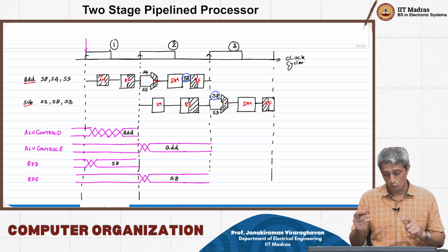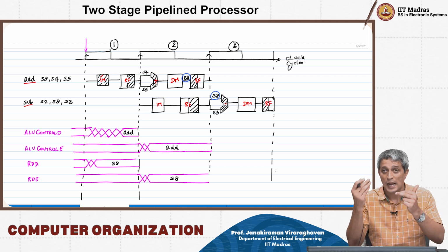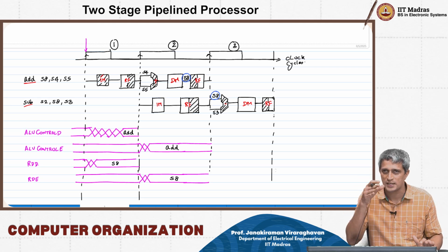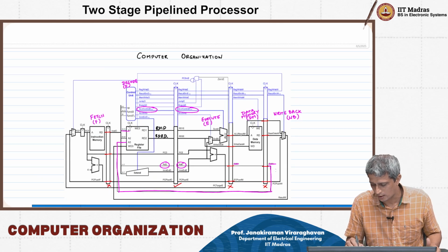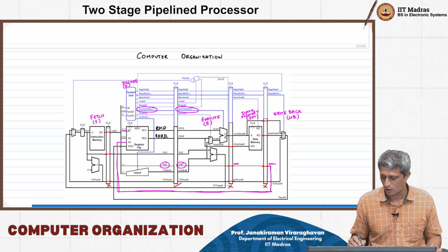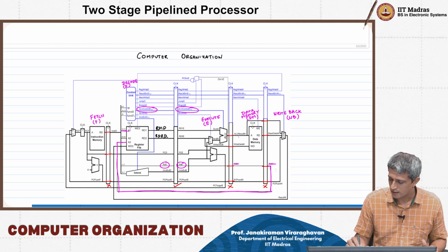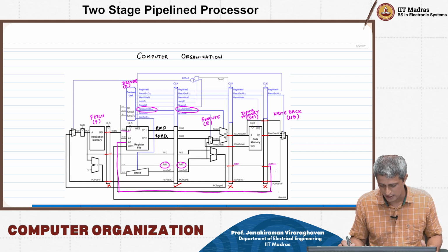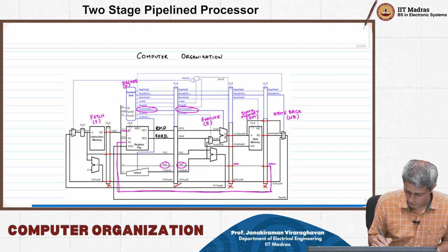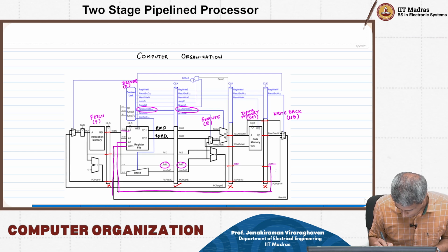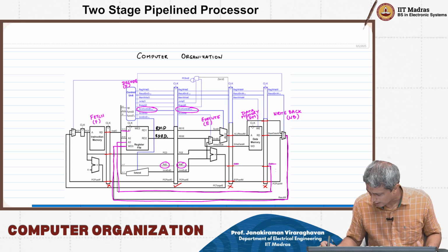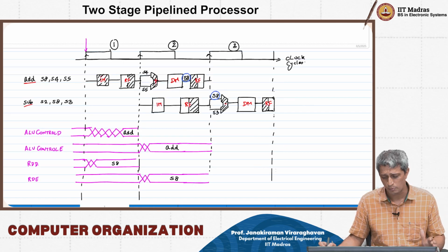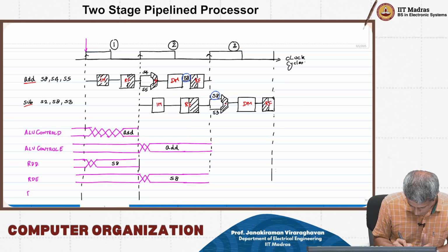Now what you are trying to do is to write the data back. The addition operation has been performed, and if you look at this whole ALU result, the output of that is called ALU result, and it comes out of all this, and then the result W is what is going to go into this WD3. So you look at this, it is going to come from this result W, right? Or I can just call it result E, because there is no write back stage, it's called result E. So I will call it result E.